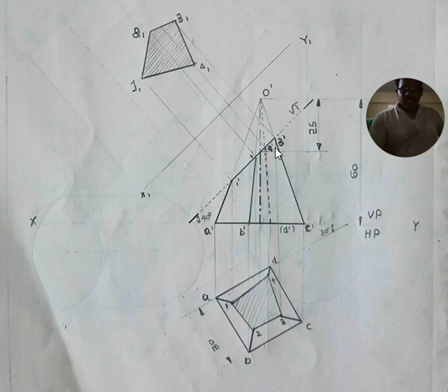Then you have to differentiate the line thickness due to sectioning. After sectioning, this square pyramid becomes two portions. The topmost small portion is removed. So the remaining shape is what the observer will be getting. Below the cutting plane line, whatever the parameters are, those have to be represented by thick lines compared to the parameters above the cutting plane. We are assuming that above the cutting plane, the small portion is removed, so that won't be visible during the front view after section. So now this is the section at front view.